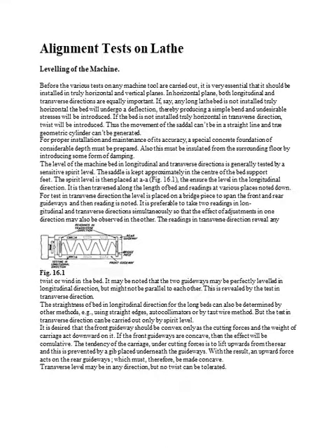In the lathe, the picture shows the idea about the bed. Over the bed, all moving parts are assembled. Hence, it is very important to test the lathe bed for its level. So this is leveling of the machine. The spirit level which we are using should have 0.04 to 0.06 mm per meter resolution.